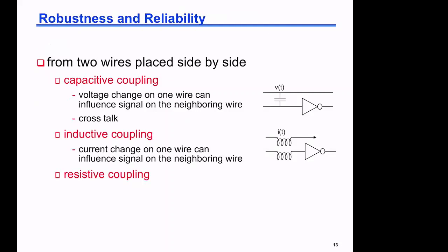Two wires can create a parallel plate and there can be capacitance between them. The wire itself, if it is long enough, under a certain frequency of operation in a certain layer, can have its own inductance. And of course, all wires have their own resistance and parasitic capacitance, as we will talk about within the chip, small and large.